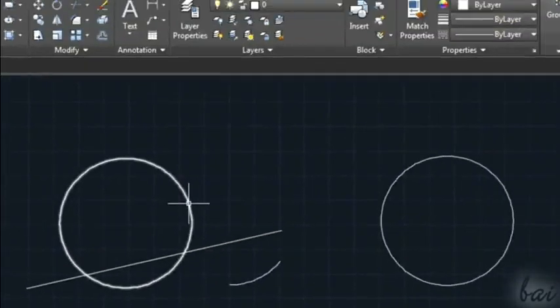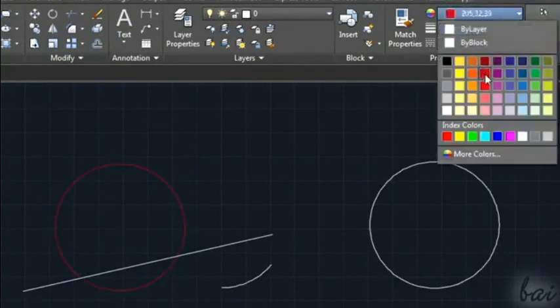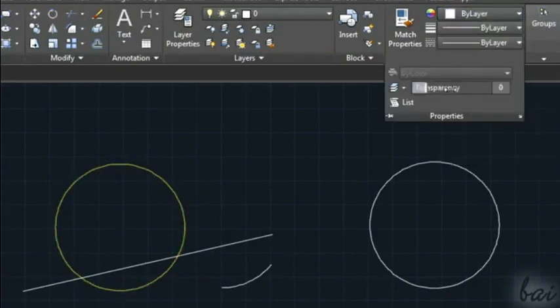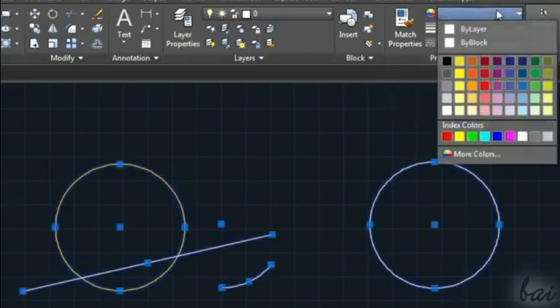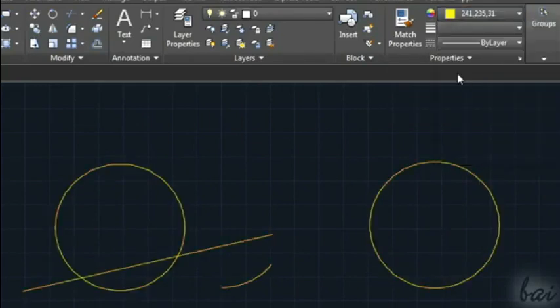Click on an object to select it. This will be shown in blue color. If you go to Properties on the right, you can choose Color, Thickness, Kind of Line and Transparency, but just for the object currently selected. If you have more objects selected, this will be applied to all of them. To select more objects, just click on them one after another.